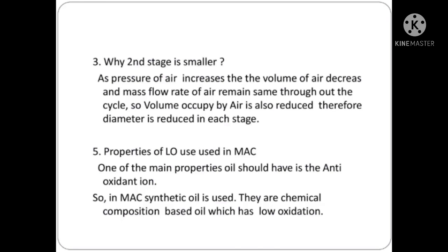The fifth question is the properties of lube oil used in the main air compressor. One of the main properties of lube oil is it should have anti-oxidation. So in the main air compressor we use a synthetic oil, which is chemical composition based and has a very low oxidation rate, thereby reducing the carbon deposition and lacquer formation.